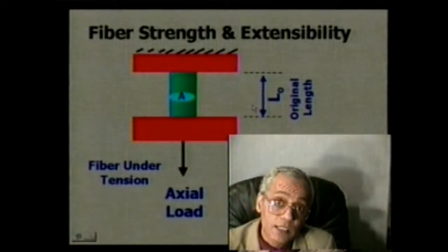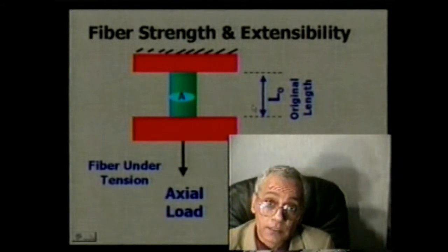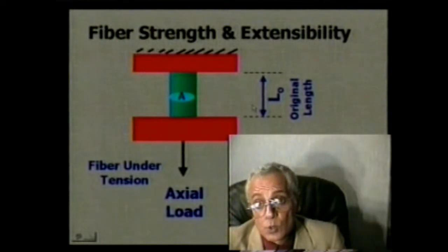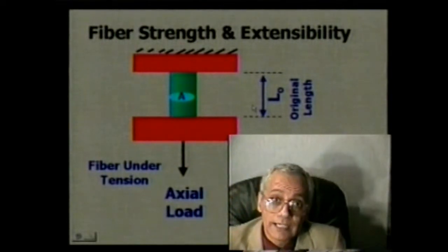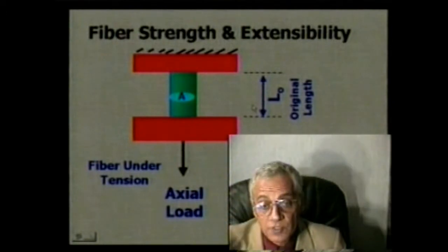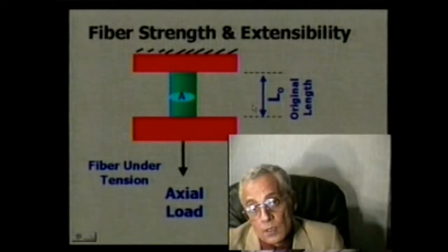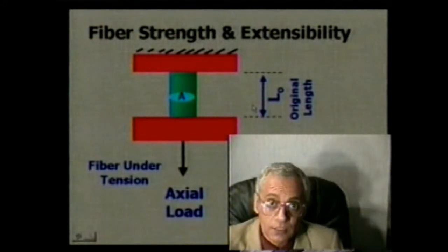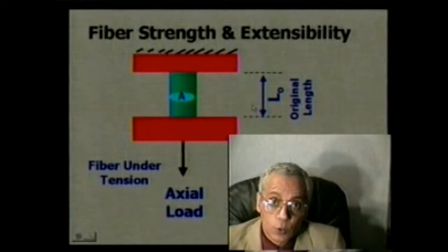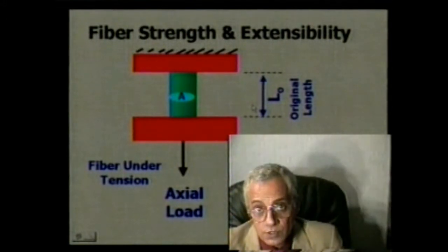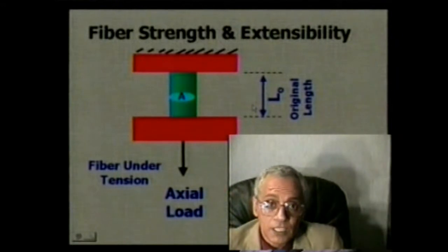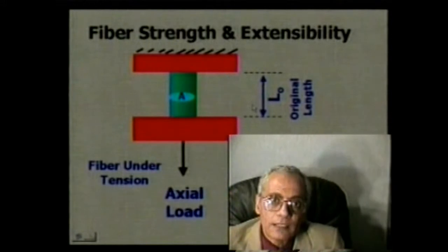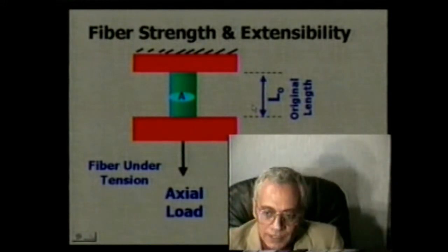There are different ways that we stretch the material under tension. We can stretch the material using the so-called constant rate of loading. That means the load changes over increments of time, or constant rate of elongation. That's where we extend the material at a constant rate with time, or constant rate of traverse, meaning that we drive one clamp at a constant speed as we stretch the material.